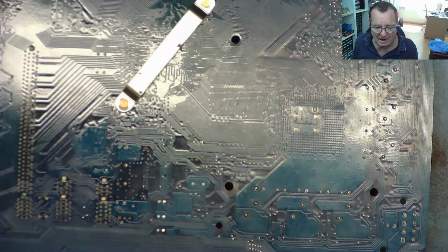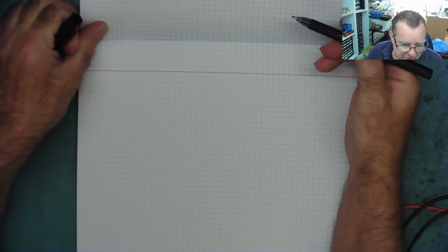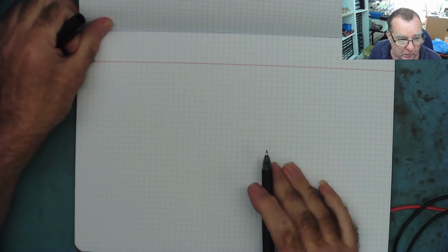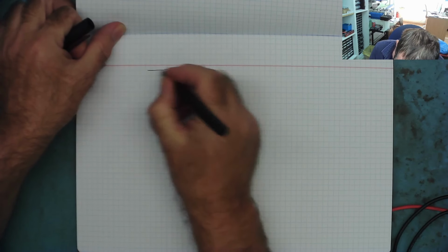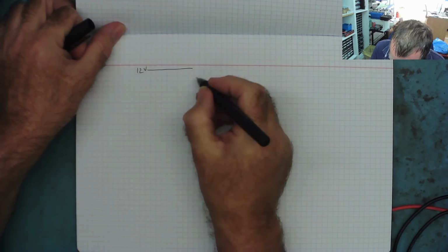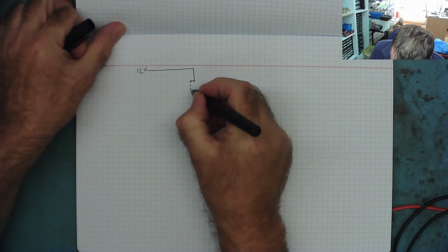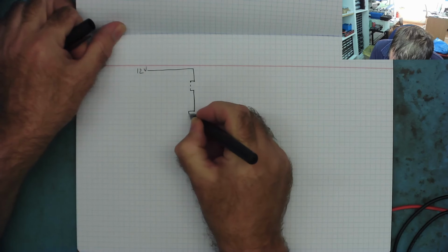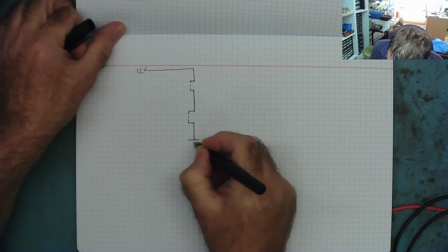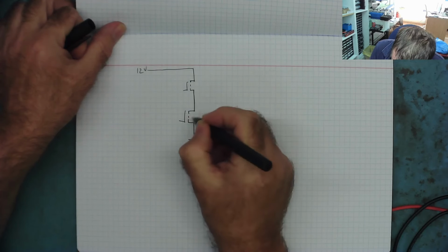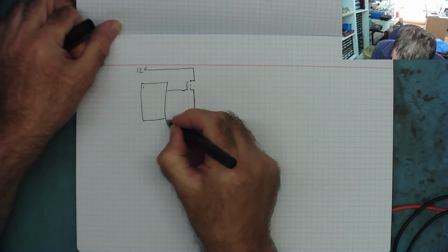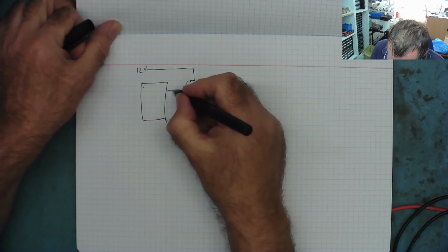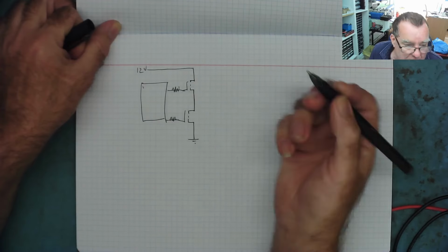Now let me explain to you how that works. To understand how this works, you have to understand a little bit about VRMs. Now, I've covered this before, but I guess there's some guys here who are new to this, so let's just do it once more. VRM, we have 12 volts coming in. We have 2 MOSFETs going to ground. Yeah. And the MOSFETs come from a controller that basically switches them on and off rapidly. Yeah, there's resistors in here and there's other stuff in here, but there you go, yeah.